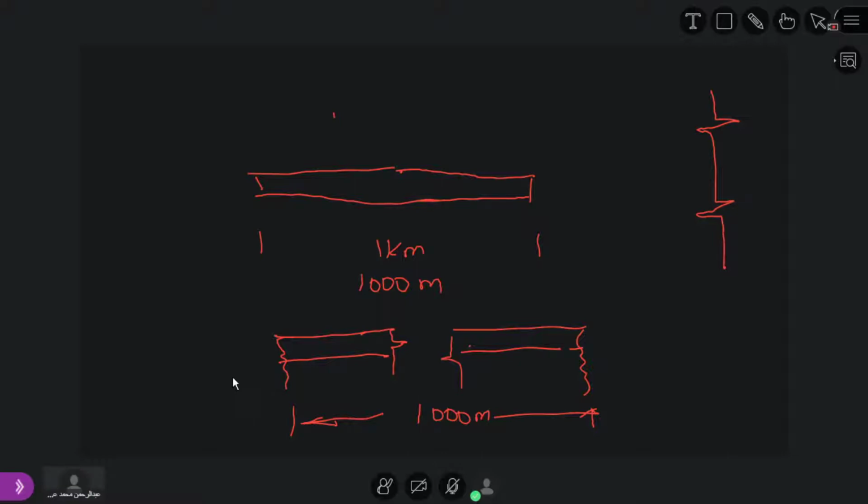No, I was saying that the thin line shows the size of the object. Correct. These lines are also dimension lines, so they will be thin. This is again a kind of dimension, because as I told you, thick lines always show the actual component, the edge of the component. Thin lines can be a dimension line, a break line, even a diameter, and so on. Do you understand? So any dimension line should always be shown as a thin line.